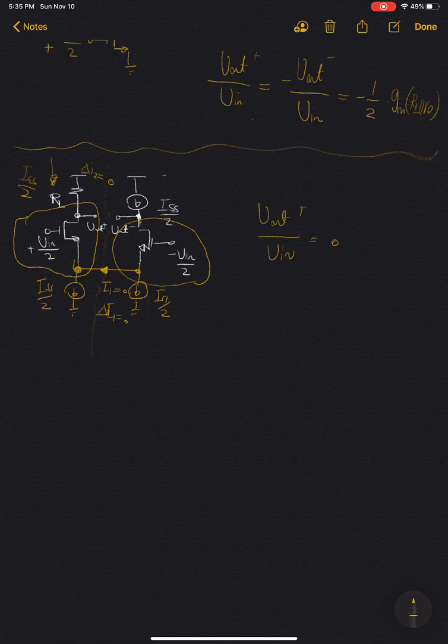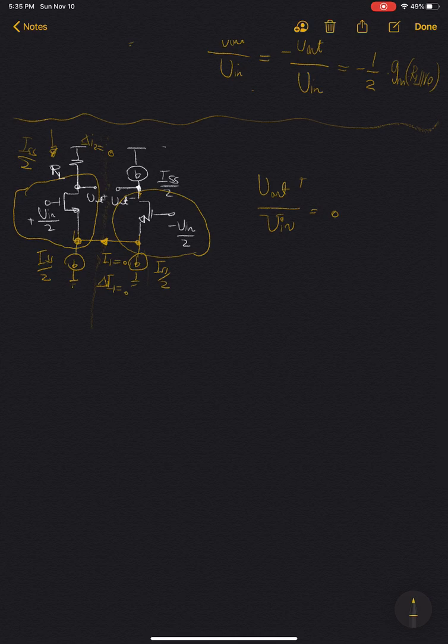Another way of looking at this would be that for every amplifier, the small signal gain can be calculated as a multiplication of the GM and R out. These are effective values. So for this one, you basically look at the output impedance, and GM is the effective transconductance of the amplifier when its output is shorted.